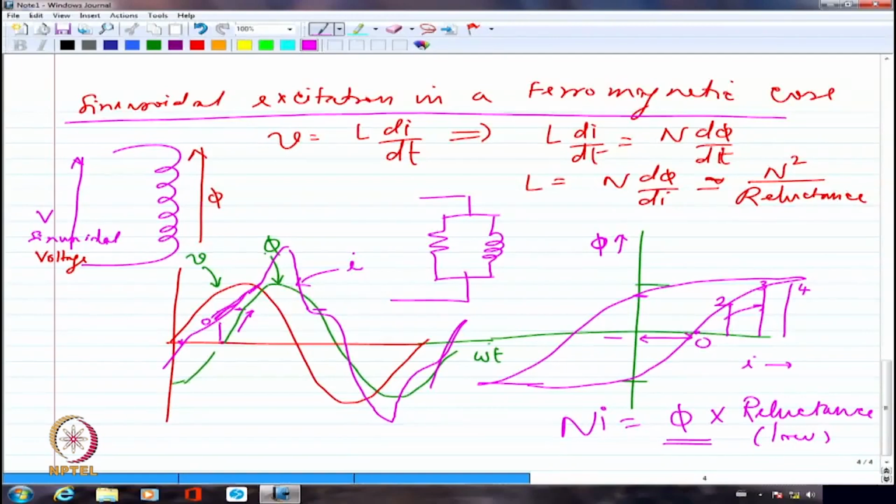One thing I have to mention is, we put them in parallel because both the quantities, that is the flux established as well as the losses due to hysteresis and eddy current, depend upon the voltage that I am applying. So if the voltage is affecting both these quantities, I should necessarily have them in parallel. If the current were affecting both, I should have had them in series because the same current would flow through both of them.